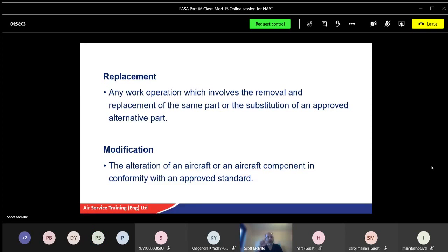There'll be a modification plate on the component, and the last number on that plate is the last modification number. In the manuals, which get updated, it will tell you to fit fuel pump part number 1234, modification ABC, or whatever the letters are.